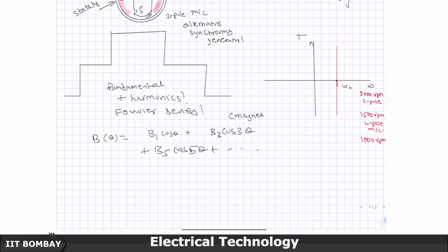But if you have two pole pairs, then you would have north, south kind of a thing. So with a two pole machine, you complete one north to south, south to north. This 360 degrees covers one south to north and one north to south, which is basically one cycle, or coming back to the original position. Here that happens only in 180 degrees, north to south, south to north happens in only 180 degrees mechanical, but